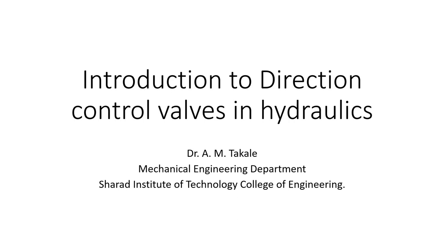The main difference between these two in the case of power transmission is that in hydraulics, we will work on high pressure, whereas in the pneumatics, we are working on low pressure because air is compressible compared to hydraulics. Oil is non-compressible, so it works on high pressure. The main elements to transmit power for hydraulic system start from a reservoir and end with an actuator.